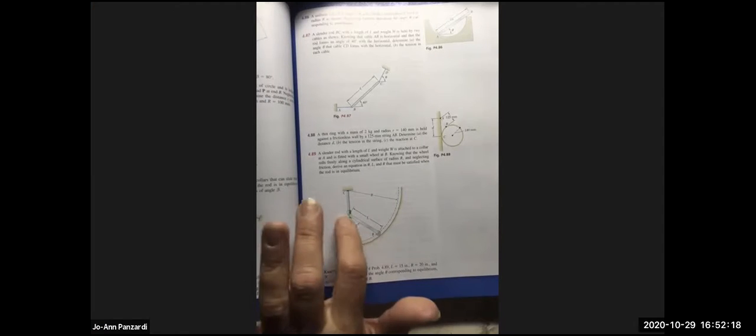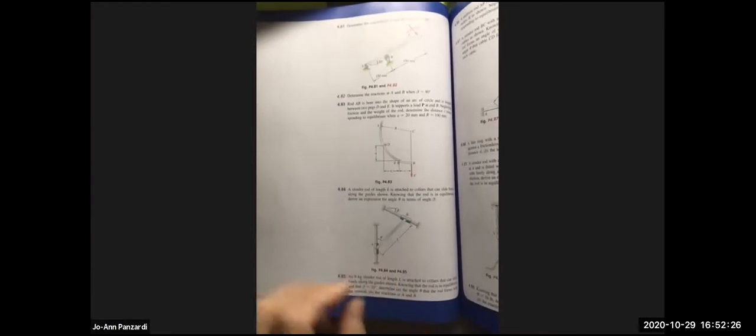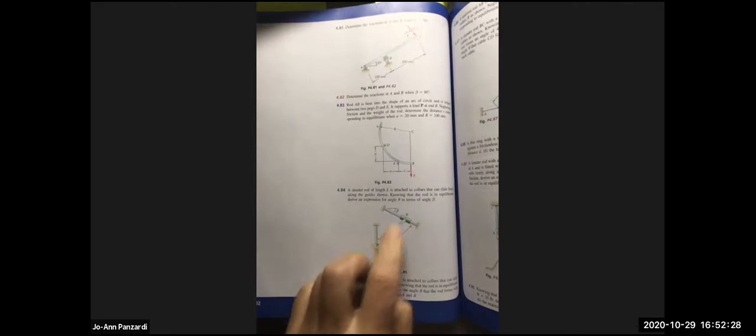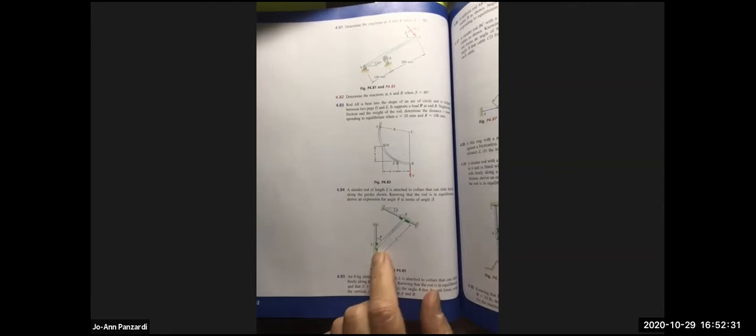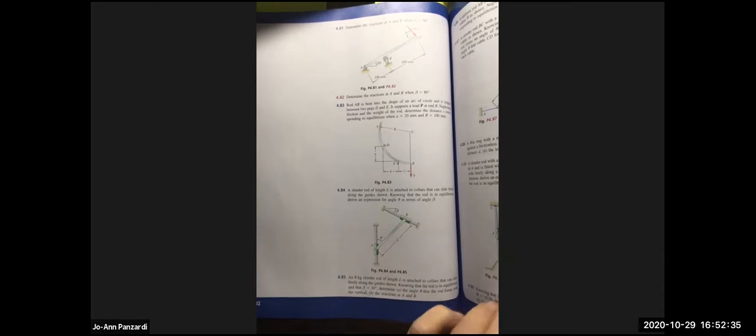But typically we ignore weight. Trusses have 2-force members and they all have weight, so let's just ignore weight for now. There it is. It's a 2-force member, the force would be right through it. Here's another one. We have 2 bars, 2 collars, pins, and here's a 2-force member. The load goes through it. Okay, I think you get it now.